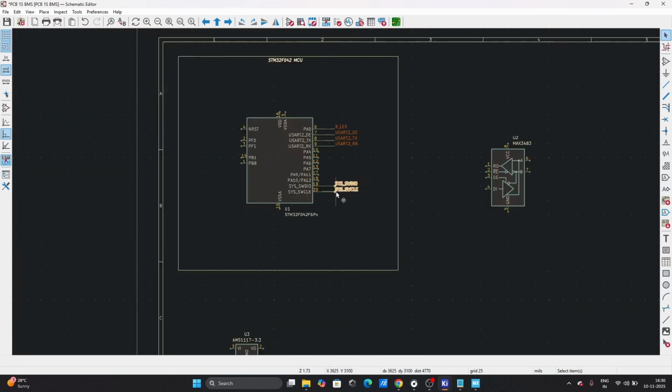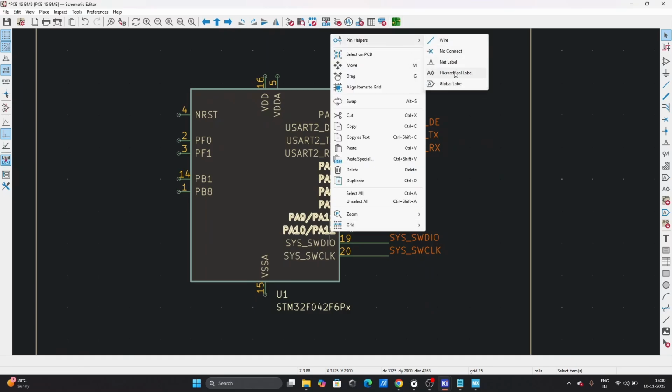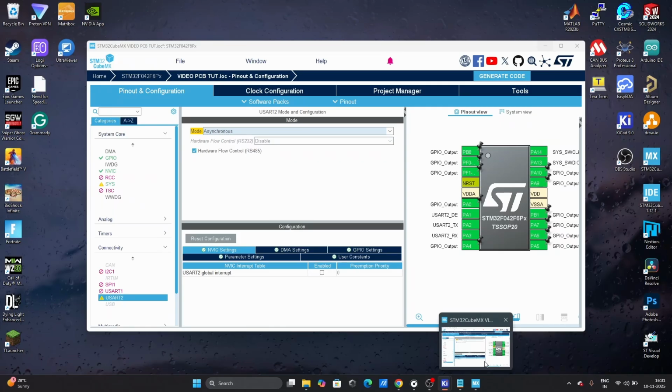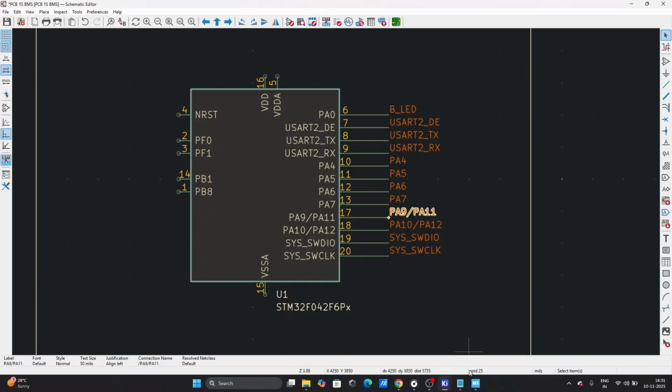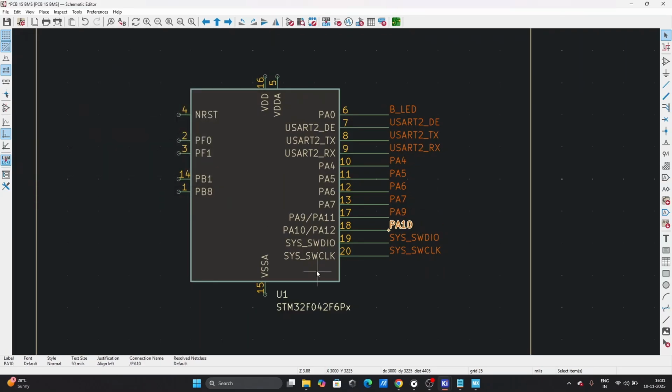You don't need to put it outside, but I normally like to do that. And this one is just keep normal labels. And we'll fix here as we don't have PA11, PA12, so we call it PA9. Same applied for these guys, there's normal GPIOs.